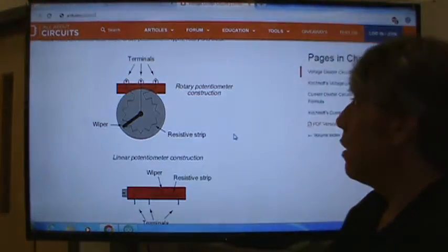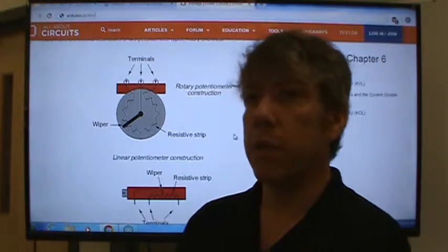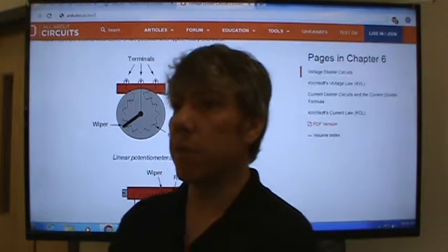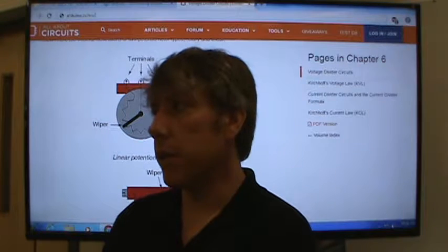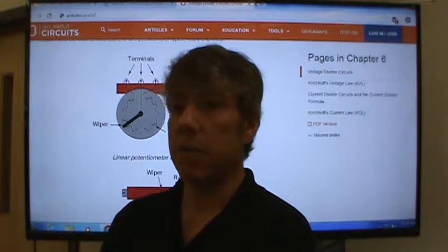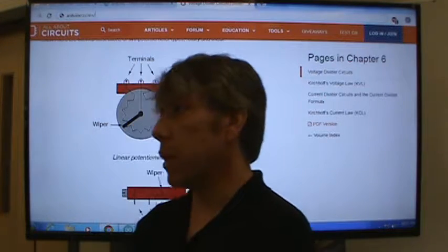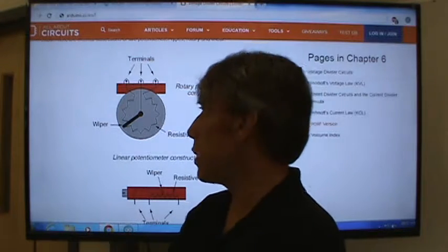Anyway. So we want to somehow get analog input into the Arduino, and for this last lab, after this we'll call them projects, but for this last lab, we've got to get an analog signal into the Arduino in order to control the speed of the stepper motor. So we'll do that very simply with a potentiometer. Okay, all we're going to do is use a potentiometer to generate a voltage between 0 and 5 volts. How do we do that?